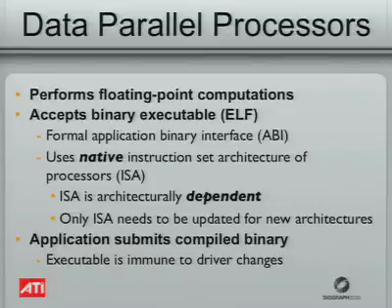The second major component is the data parallel processors, which perform the floating point computations. So one thing that I should probably mention here is that we're only interested really in floating point. So all of the memory formats that we expose currently are just float 32s. So you're allowed to do single, dual, or 4 component float formats, and I'll get into more detail on that later.